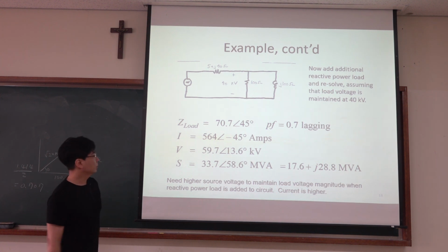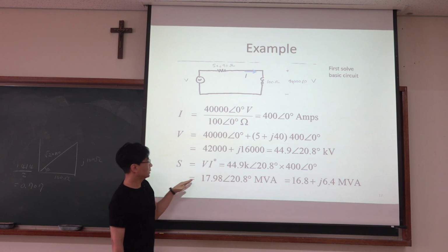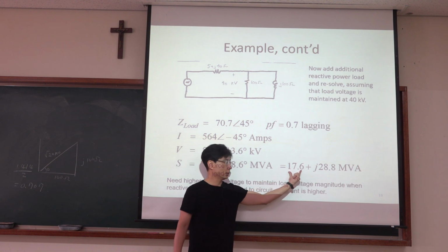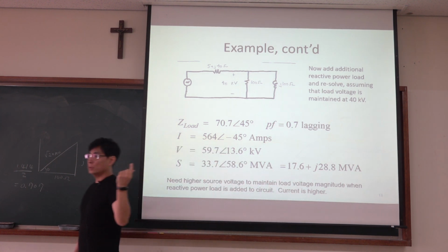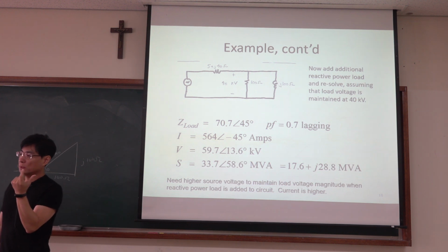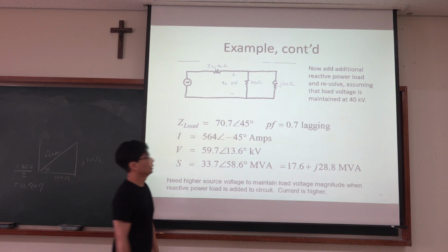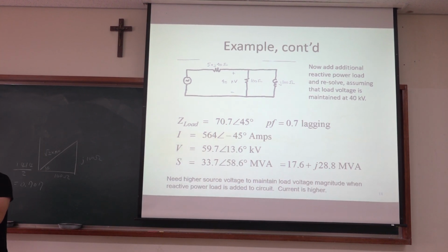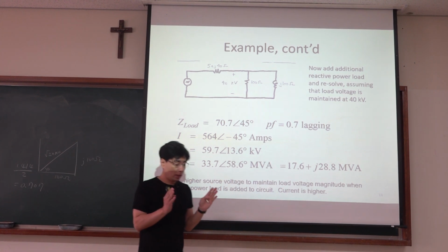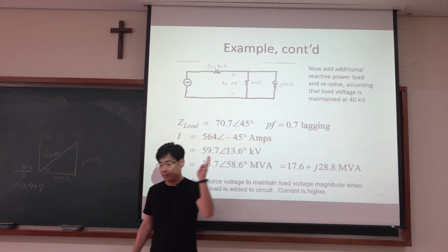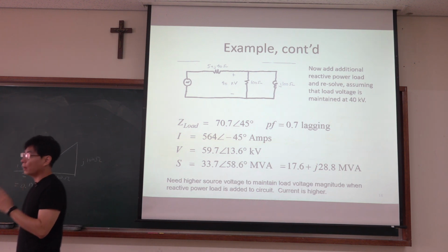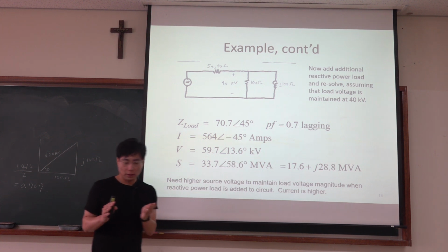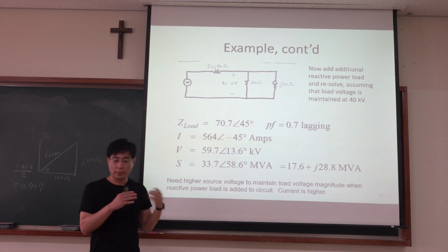Also, when you look at the complex power at the source side, the active power and reactive power, the required active power is increased. The reason is that we have more power losses in the transmission line. And the reason is that inductive component, the power factor changes. In the ideal case, the power factor should be close to 1, like 0.95, almost close to 1. It is not easy to make it perfectly 1 because the load has some inductive component.